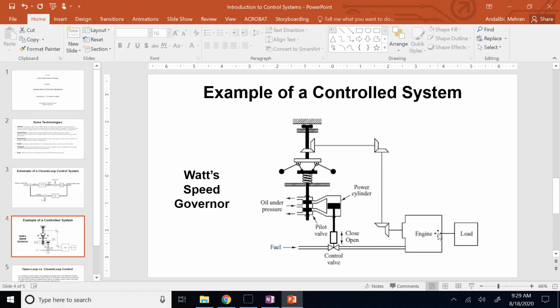Because there was a mixture of air and fuel, now it's exploded, created the pressure, and it moves the piston down, so that pressure is released and converted into kinetic energy for the crankshaft. So the piston goes down and then the exhaust valve opens, so the rest of the mixture gets out of the cylinder. The piston is down, and what happens? Yeah, you have a relative vacuum created inside the cylinder.